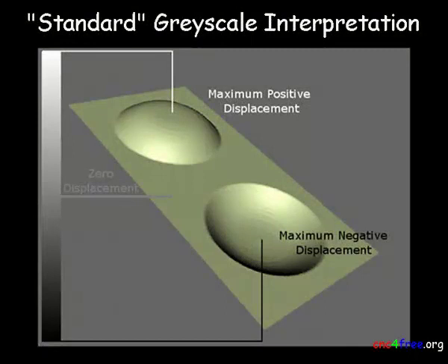Only 256 values are available in the greyscale range. Mesh displacement and image to toolpath software process grayscale using a common standard. Mid-gray is processed at the 0 position. White represents the maximum positive height value. Black represents the maximum negative height value. Actual values derived from gray levels are calculated using a specified maximum value.